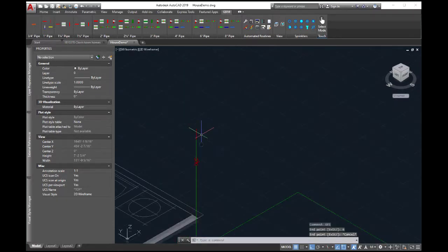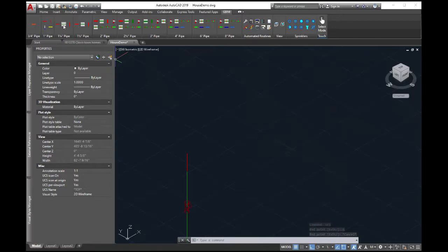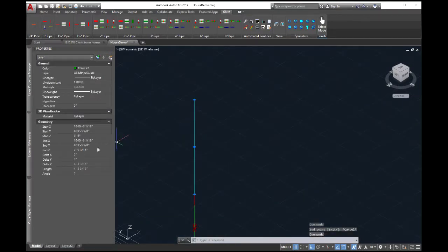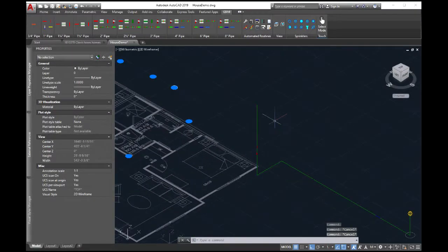We'll call that good. And then back to our riser pipe, our normal riser pipe, which right now we're using this pipe. And we'll take this all the way up to, and once again, I just kind of terminate it, and then I go over here and take its NZ, and I'm going to make that 11 feet. That's basically a foot higher than the sprinklers. So that's what we're going to do for the moment.